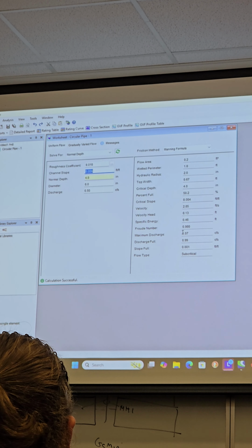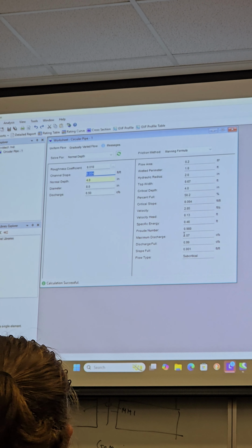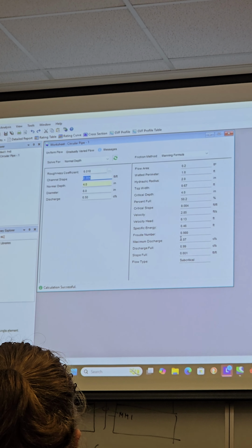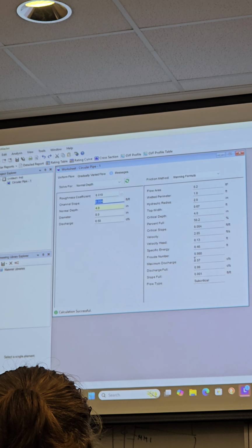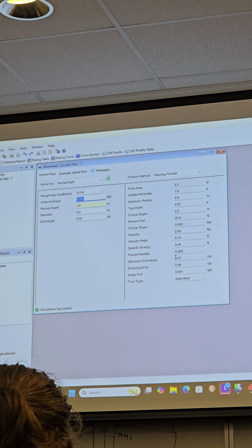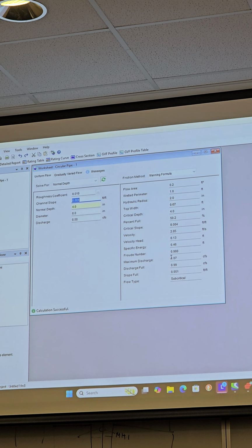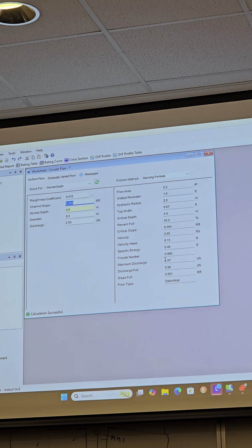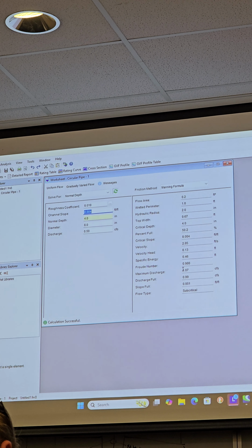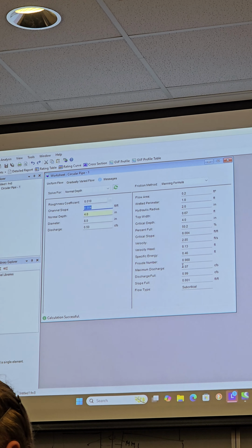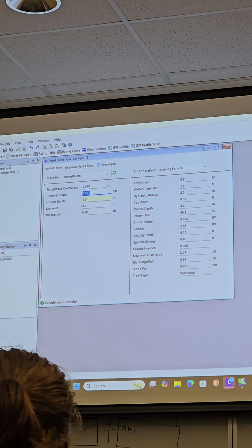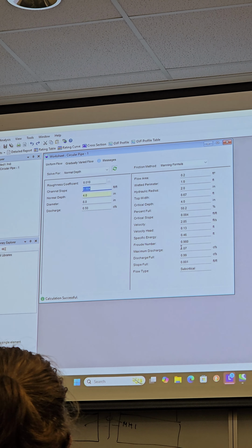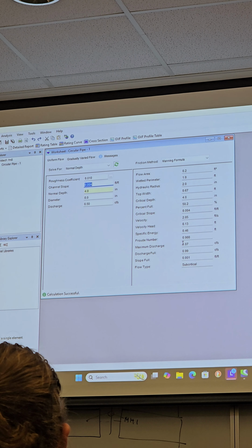Is the lateral a specific size as well, like 8-inch minimum as well? The lateral would be 6 inches. Yeah, and again, most residential units, you're not producing a lot of waste effluent. I guess if you had a really large family or a lot of people that live there, you obviously would produce more.